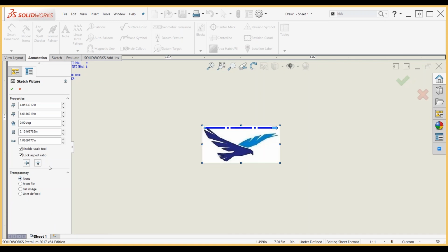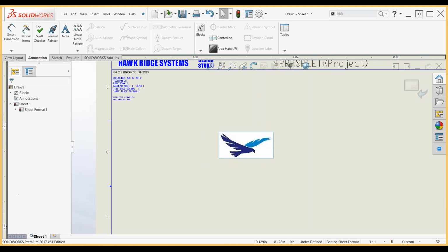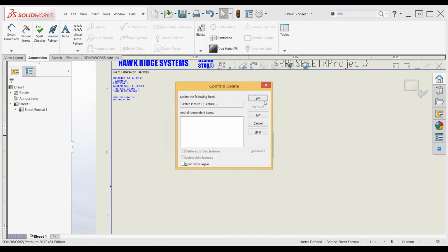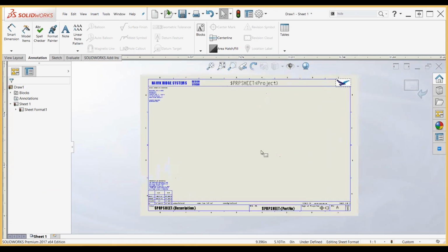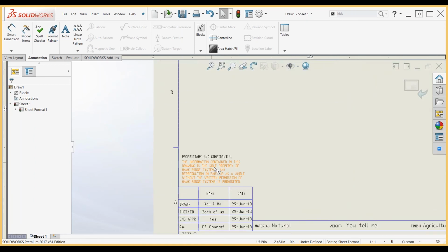So what I'm going to do is put a document status watermark on this drawing file here. I'm going to make it really big so it's impossible to miss, and I'm going to put it as this nice little gray color. But I'm not just going to write words. I'm going to link it to a custom property here, and I'm going to leave it on this current document, but I'm going to make a new property called document status.